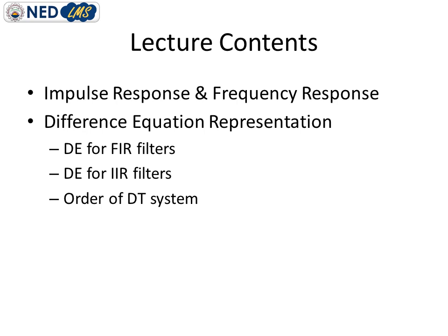So the poles and zeros will be decided by the order of the system, or in generic terms we can say the sharper response means the order of the system is higher. So if we need a sharper response from any system, then we must design a system which has a higher order equation.